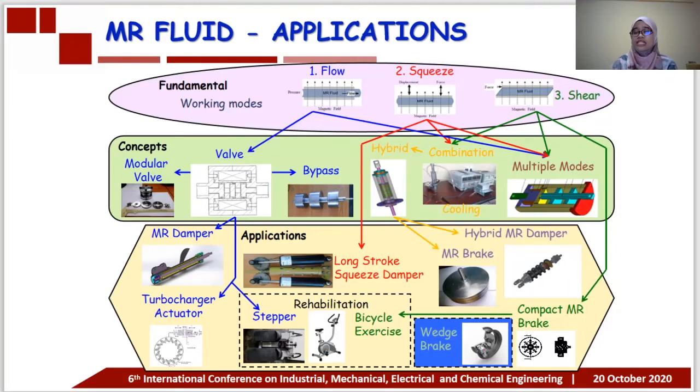Because of this changeability of MR fluid in milliseconds, MR fluid has wide potential to be applied in various applications depending on the working modes as shown here, either flow mode, squeeze mode, shear mode, or a combination of these three modes. So MR fluid can be applied for MR dampers, turbocharger actuators, hybrid MR dampers composed of multiple modes, and also has potential to be applied for rehabilitation with stepper and bicycle exercise that focus on a compact MR brake.